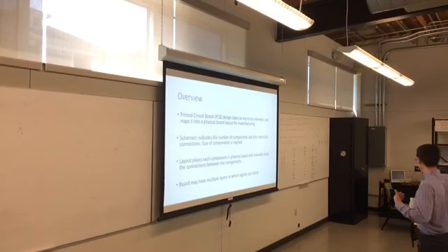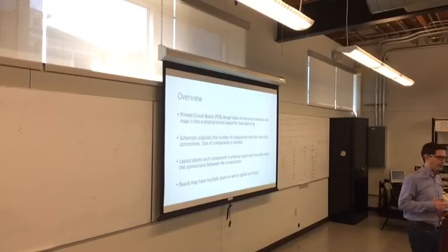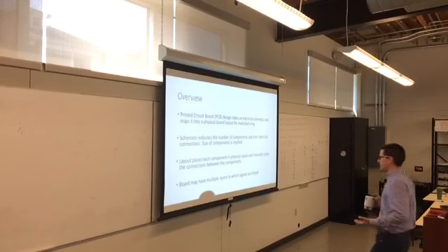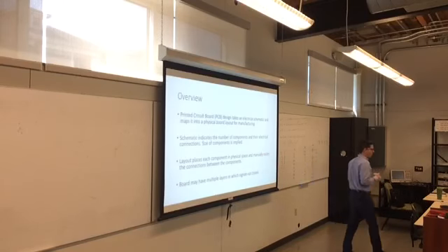The layout is determined by how you physically route all those wires. So the second half is a board layout. A board layout says, well, you have all these components, they have some physical size, and you have to tell me where these wires go. So you have to physically lay the wires on the board to route the signals around. So the schematic is the number of components, and the layout is physically where they go.